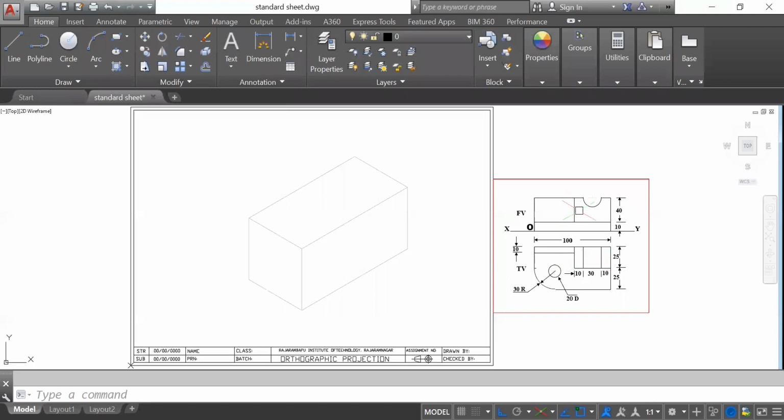So this part, if you observe from the front view, it would look like this. One hole is there, a half circle, and it is not throughout the width. Yeah, it is up to only 50 mm. So one rectangle for this circle and other two rectangles for this one and this one, having 10 mm by 25 mm. Getting 30 by 25 and 10 by 25. Okay, so this is how it is required to observe the drawing, and then we have to plan.